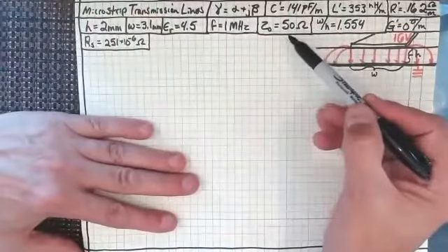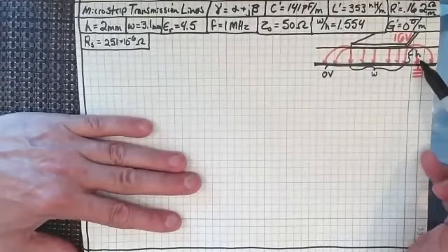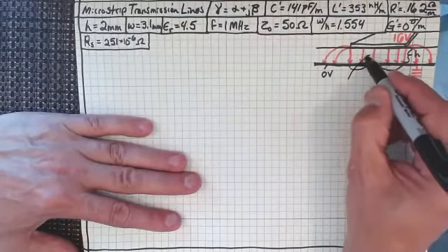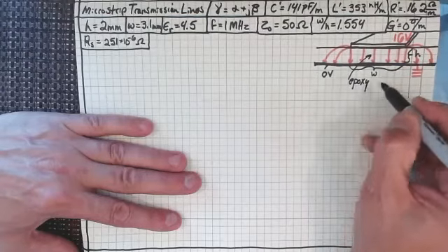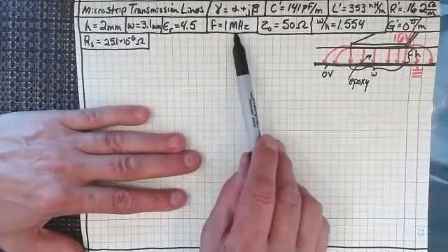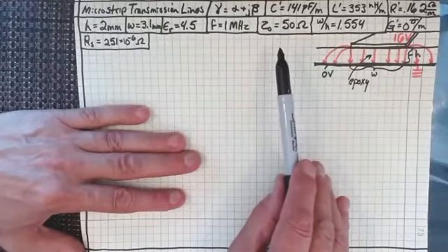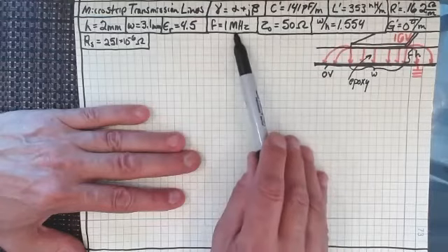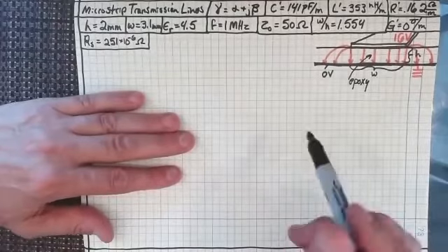We originally set it up as Z0 is 50 ohms. We had H, which is the thickness of the epoxy printed circuit board, and epoxy's relative permittivity is 4.5. We're putting a frequency of 1 megahertz through there. I'm going to compare this later to a frequency of 10 gigahertz, which would be 10,000 times as high, and you'll see that still the lossless approximation applies.